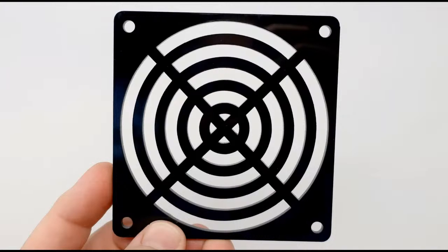So I find that with a DXF, and sometimes other files, depending on how they were created or how they were generated, especially a lot of the 3D rendering softwares out there these days will export a 2D object as a DXF. And again, you're going to get sometimes hundreds of little line segments. And so the Smart Fill tool is ideal for just clicking in the center, duplicating that object, or you can use the boundary tool as well if it's just an outline. In this case, I needed to do both inside and outside, so the Smart Fill worked better.